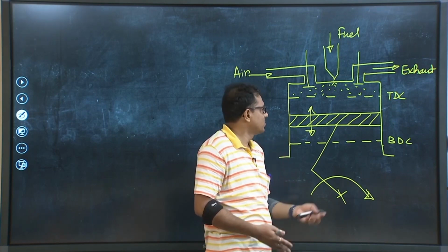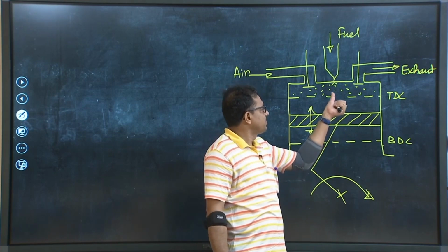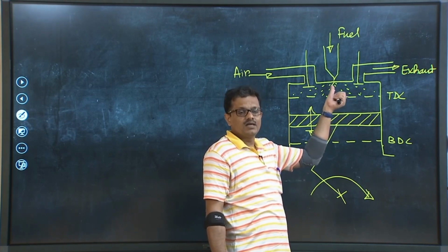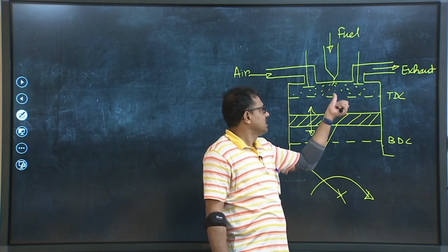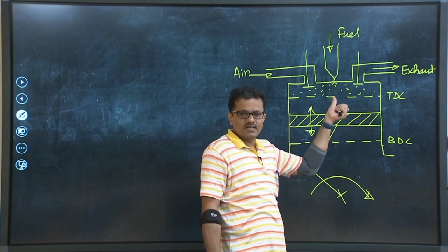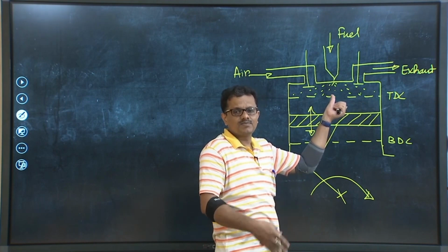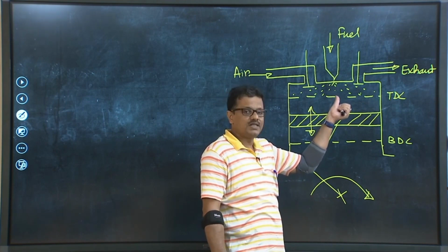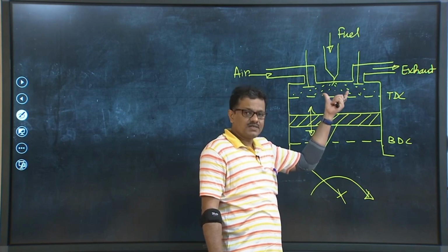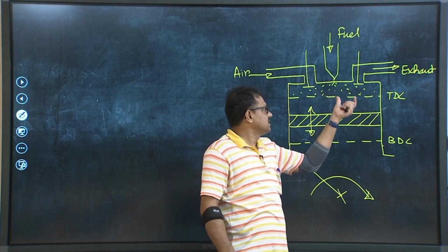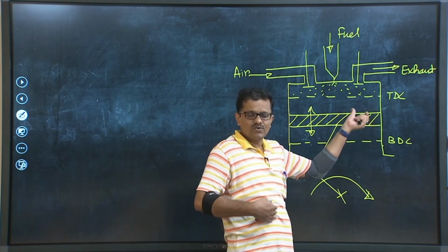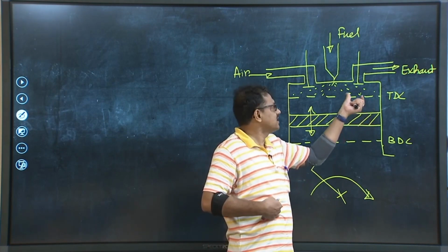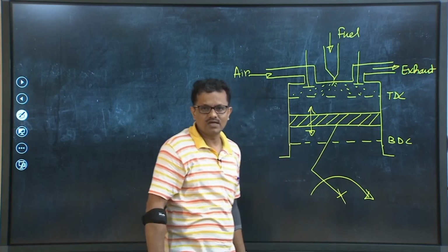Instead, we can assume that the pressure developed during the supply of the first phase of fuel takes part in the combustion, and because of this first phase of combustion there is a rise in pressure. When the piston comes back from TDC to BDC, you can argue that the pressure will fall, but by then the second phase of combustion has already started.